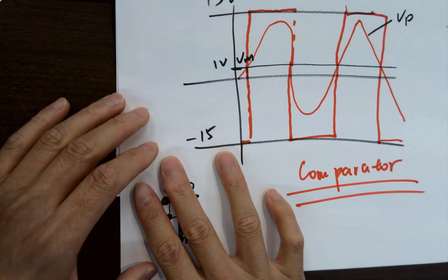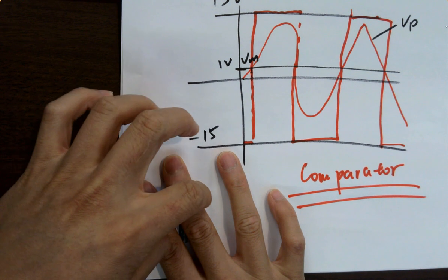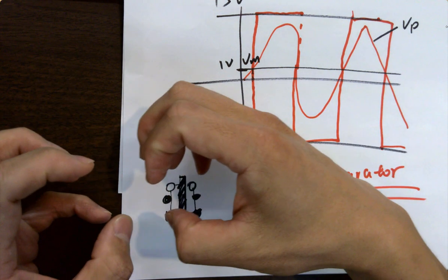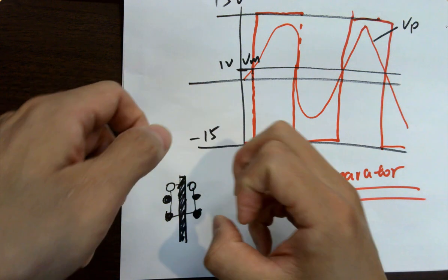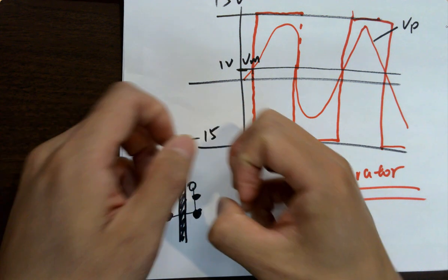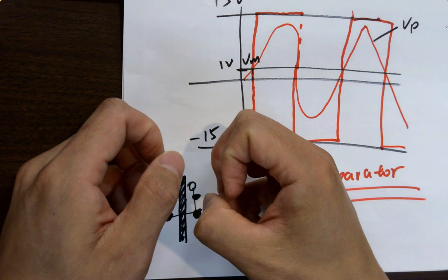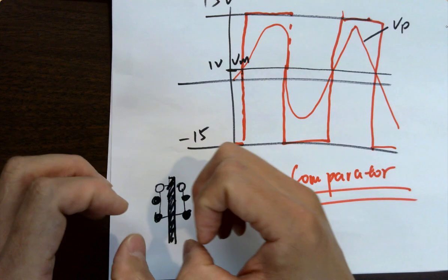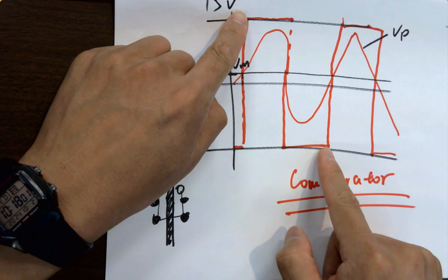The left. Wait, it's the right wheel. The right wheel should be off, right? And this one should keep on. So whenever it's out of track, you want to stop this one and keep this one rolling. So it pulls it back. All right? Because the circuit can do this adjustment really quickly, it's keeping the car on track. That makes sense? Okay? And you are using this pulse whenever it's out of track. You keep one of them on and turn off the other wheel.